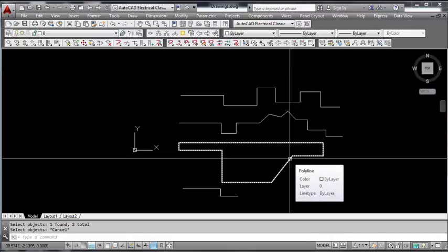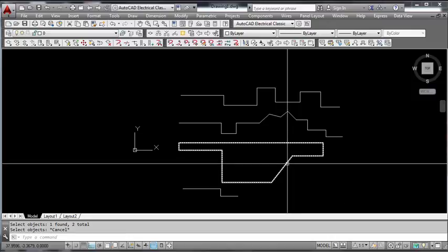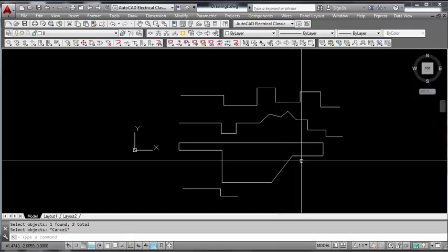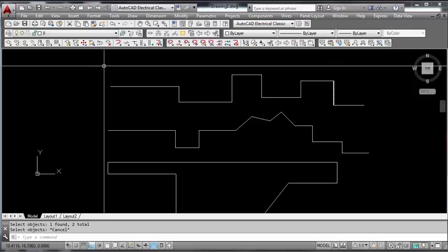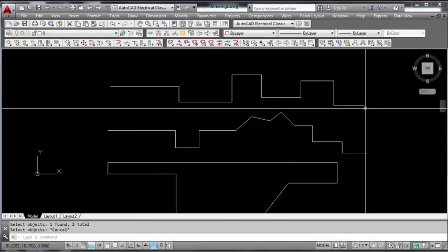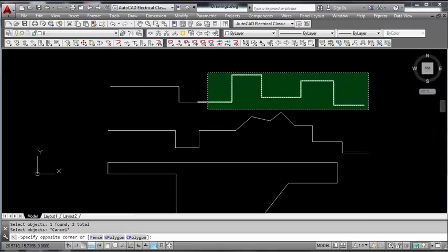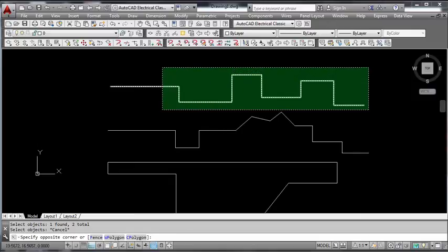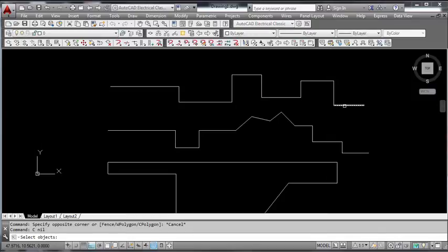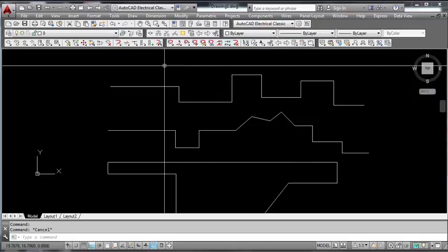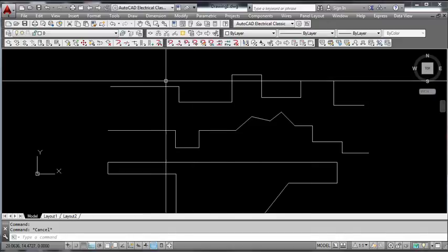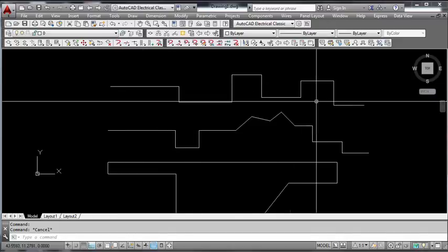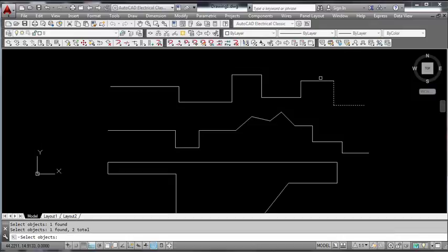So normally, in big drawings, mainly in civil drawings, what we do is we make the boundaries, we make the roads and many other things using this polyline, because sometimes we may require to change the layer of this whole line, the color of this whole line, even the line style of this whole line. Then if we make this with the line command, we have to pick each and every line individually.